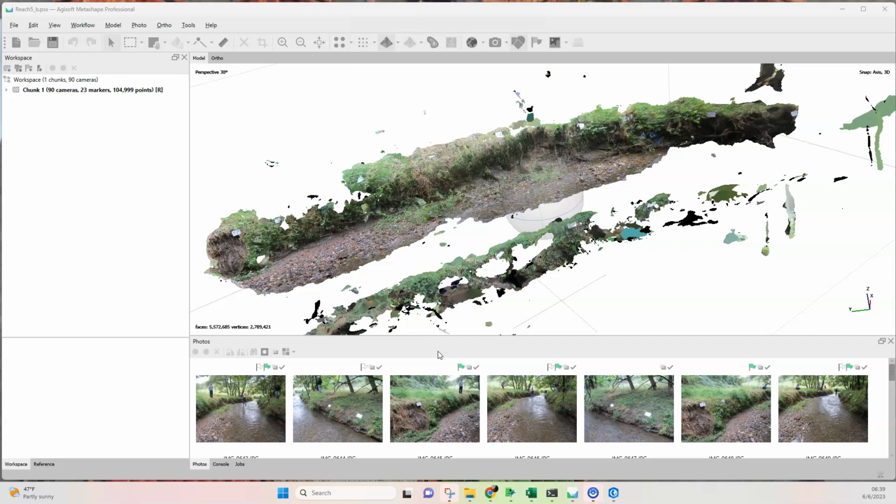The other thing you're going to do is take the result of this and imagine our point locations for the buckets, for the stakes themselves in this reach, are about here where my cursor is, and about here. And when you were there at the creek, this group would have stretched a string across the stream. Now what we're doing in the deliverable is we are creating three different renderings of that cross section. One that mirrors, using Google Sheets, the process you use to measure with the string down to the water surface and down to the bed of the stream.